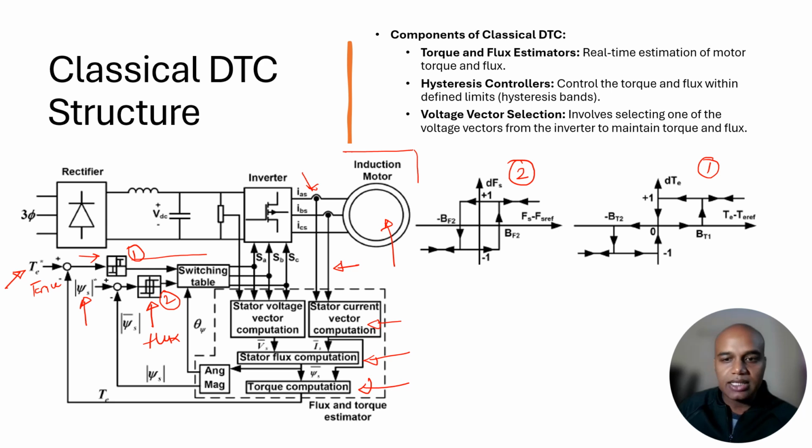So what happens exactly is that I just want to control my motor torque and speed. Therefore I am decoupling the torque and the flux from the taken stator voltage and stator current, and this measured value is compared here. This is the comparator. It is compared for both the torque and the flux value, and the error goes into these two. So the torque error which is produced, let's say delta Te, and similarly delta psi s, the stator flux, shown over here in this figure.